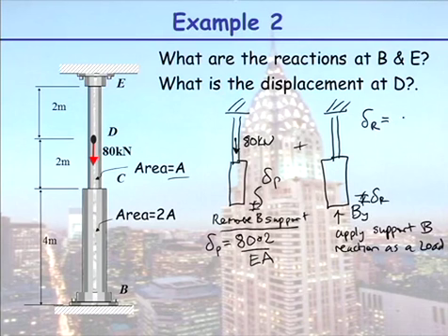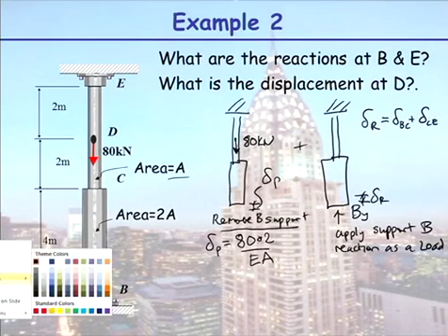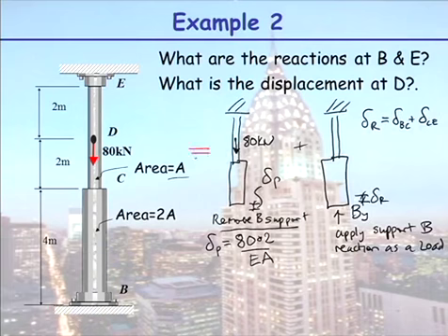So I'm going to break this up into the deflection in BC plus the deflection in CE. Now please take note, I'm not applying the 80 kilonewton here, I have to apply it once, because what I am saying is that that is effectively equivalent to my 2 redundant systems based on the compatibility relationship that the 2 deflections equal 0.